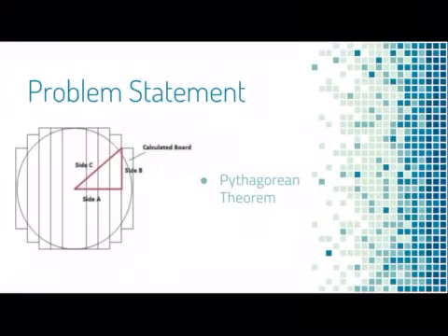The design for each potential size of flanges follows the Pythagorean theorem as the figure shows. The construction is started with the center board and is built board by board until all dimensional requirements are satisfied. Set C, for instance, represents the radius of a given flange plus a 1-inch buffer. This 1-inch buffer is added in case of error by the chainsaw when the flange is cut out of it. Set B represents half of the length of the next board's minimum length required to assemble the blank.